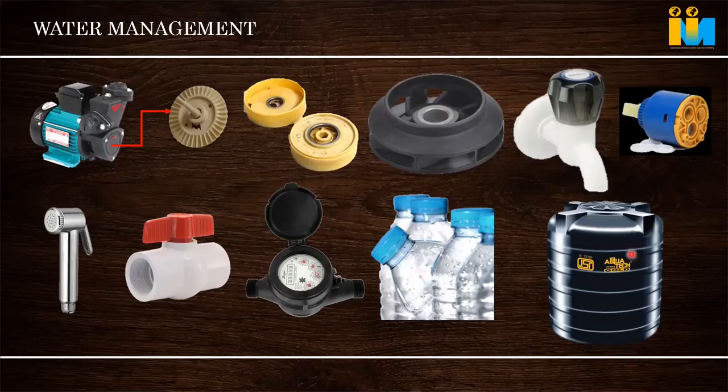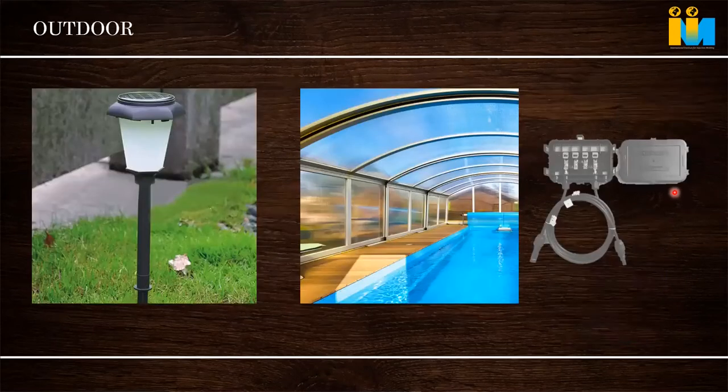Okay, these are HDPE applications, like water tanks and all. Normally HDPE is molded, and internally they'll be doing some coating. Fillers will be there in this also. 30-40 percent of filler will be there, because it's highly cost sensitive, bulk products. That's why water tanks and all. Even chemical tanks are also made of semi-crystalline material. We cannot go for amorphous. That's the bottom line.